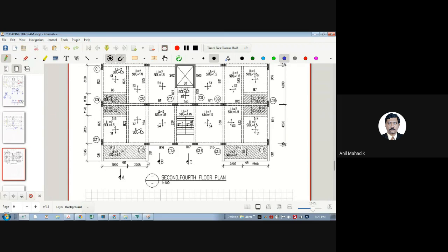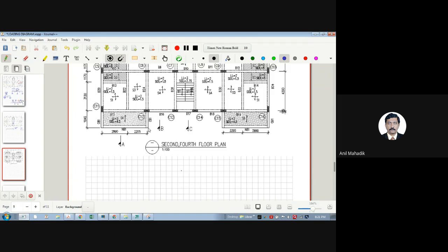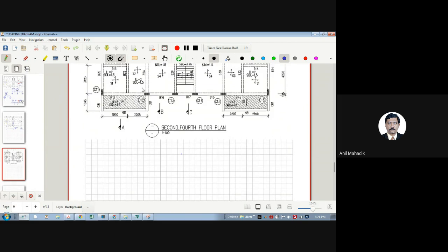As it is a balcony, you know what kind of beam this is? ये वाला beam कौन सा है ये? There is no support of this beam, no? Cantilever. So it is a cantilever because this NB1 load is transferred to the cantilever as a point load and then it will go back, right? So if I ask you to draw the loading diagram of this CB1 and say B24, समझो मुझे ऐसे निकालना है तो tell me कैसे दिखे?